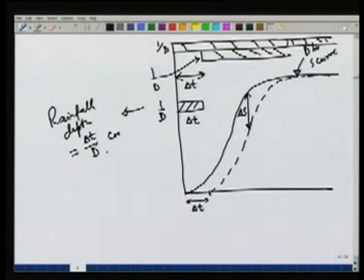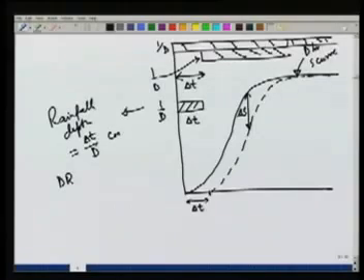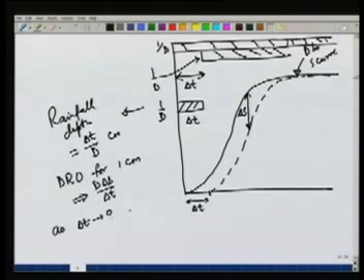So if we have delta S due to a delta t over d centimeter rain, we can find out what will be the ordinate due to 1 centimeter of rain by using the principle of linearity. So the ordinate DRO, direct runoff ordinate, due to 1 centimeter of rain can be obtained from delta S, delta t and d. So let's write it in terms of first finite values, d delta S over delta t, and then we will take the limit as delta t tends to 0. We can get dS over dt.